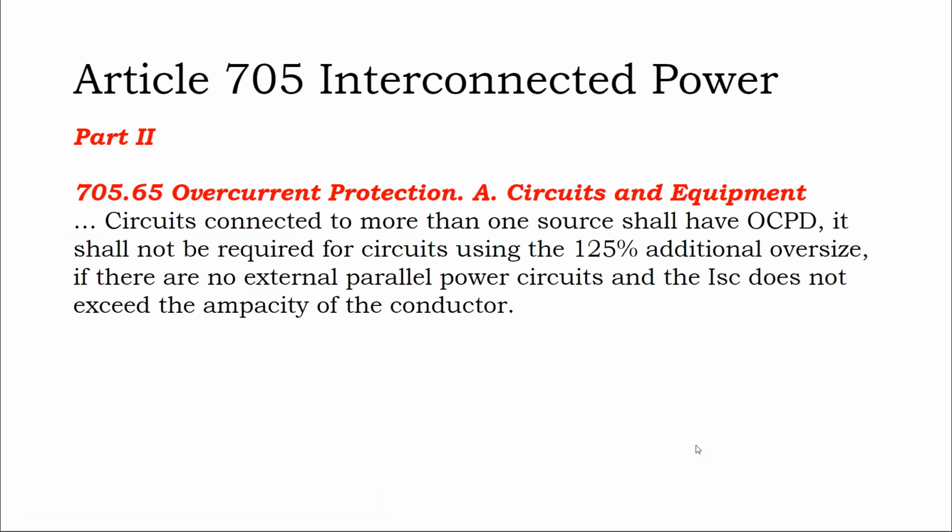I guess what that means is, if you have an output current and it's rated for 40 kilowatts, and you put a fuse in there, let's just say it's an 800 amp output system, and normally you size it to be 25% more than that, but if for whatever reason the manufacturer says put in a 900 amp fuse in line, then you could size it for 900 amps. That's a rare circumstance.